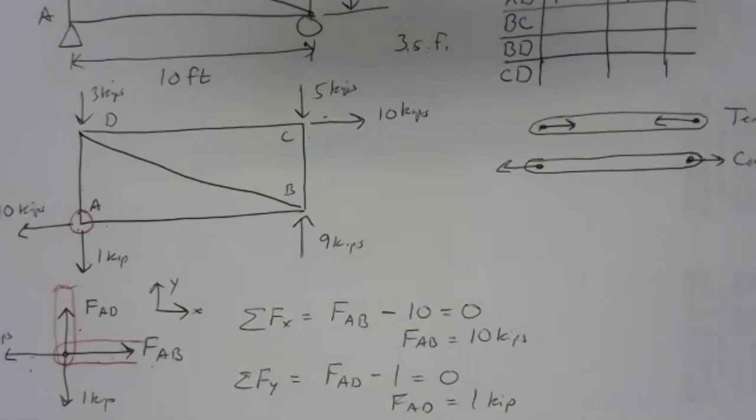So that's joint A. The math wasn't too hard on joint A. We got a nice simple free body diagram, which tends to happen when only 90-degree angles are involved. And we had to interpret tension or compression. We'll go back to the physical discussion here once we're finished with the problem and take a look at why member AB and AD have to be in tension.